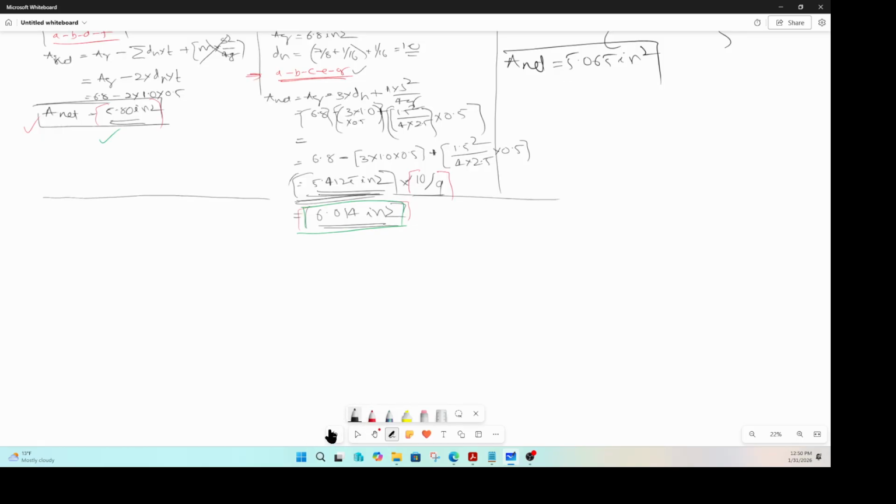So the load carrying capacity based on yielding. For yielding, you take 0.9, that's your factor, times Fy times A gross. So that is nothing but 0.9, Fy is your 36, and A gross for one angle was 6.8. If you do that, you see 244 point, sorry, 220. This would be 220 kips.